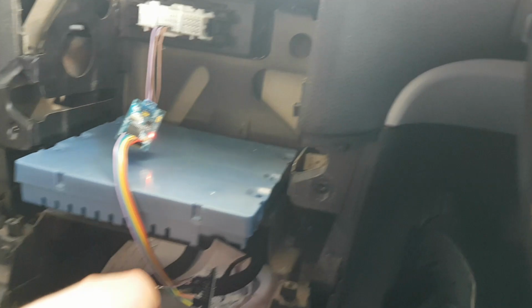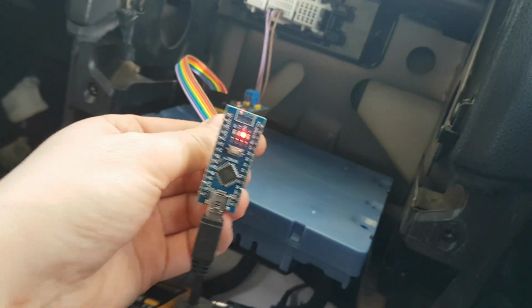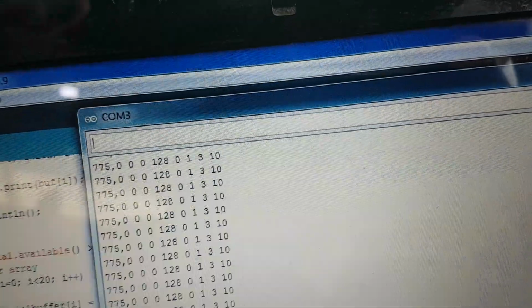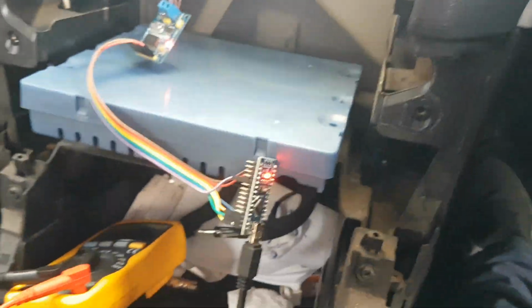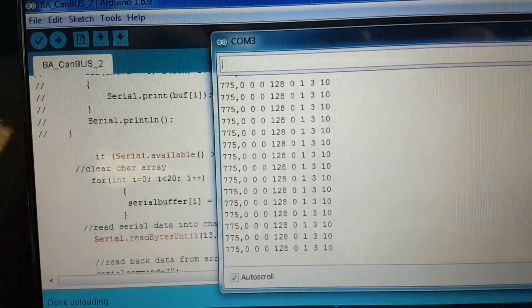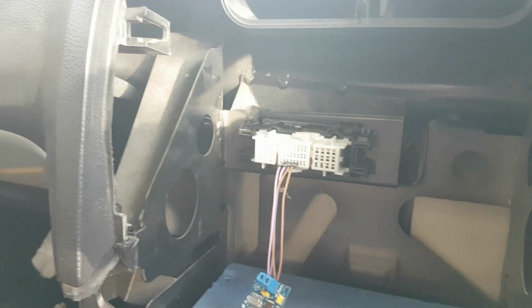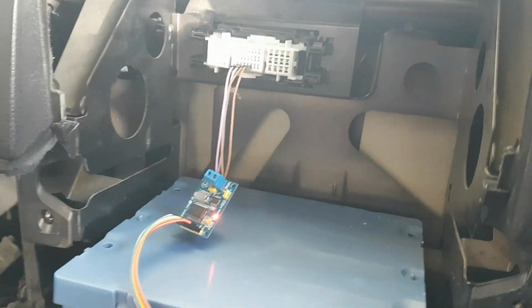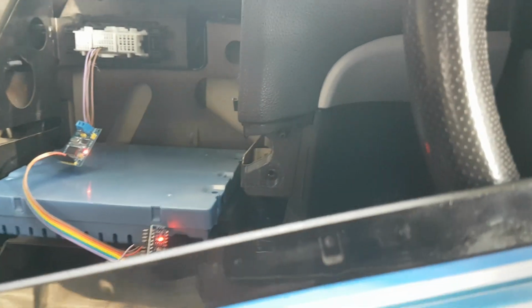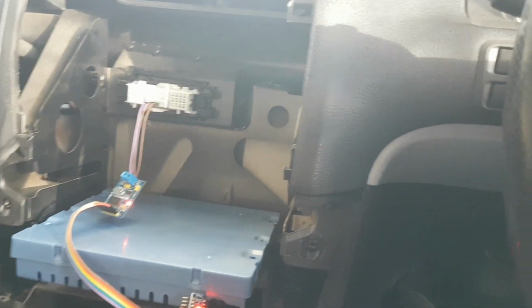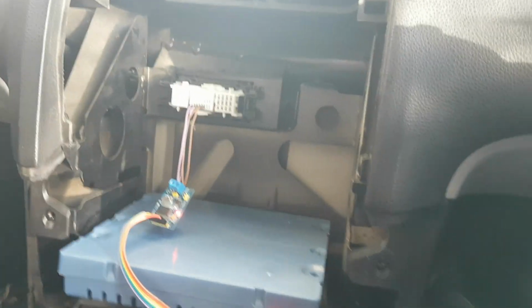I'm going to switch over to hardware inputs, so bringing a digital pin high or low to trigger the door locks and whatnot, and then I'll use a Raspberry Pi wired to the Arduino to pull those pins high or low, and that may solve the serial issue. I'm not sure, but it's a work in progress. This is certainly more progress than what I've had, because previously I was just dumping those codes on the CANbus. It wasn't really building the string, I was just manually inputting them and sending them out.